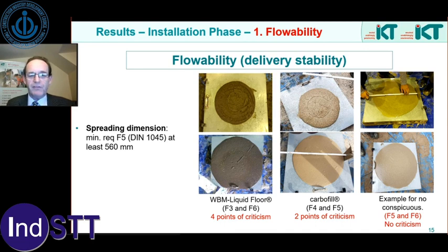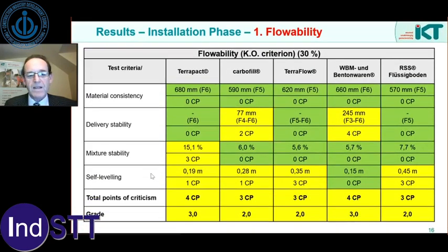the most basic test is done as you might do with other types of flowable concretes. It's spreadability. How wide does it spread when a certain amount is poured from a particular height? And we looked to see how that would function. And there were a range of issues as well to do with it.